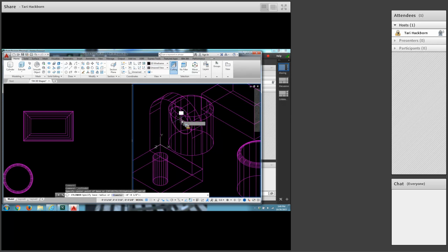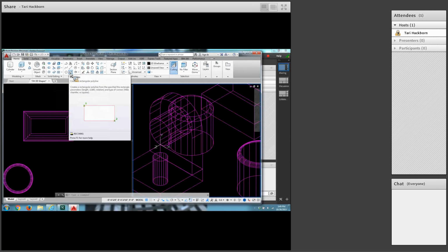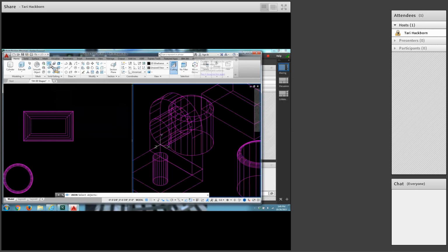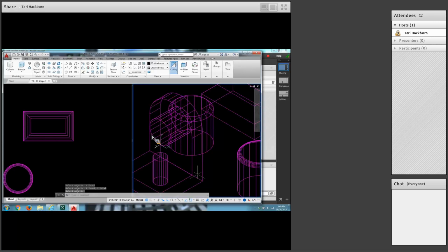Sorry about that. Gets a radius of a 1/4 inch, and it has to come out in the positive Z direction 1/2 inch. Did a lot of thinking there, didn't I? Okay. Now you're going to do union and subtract right up here. Okay. Union. Okay. Union. And you're going to pick the back and the bottom and press enter, and they're unioned together.